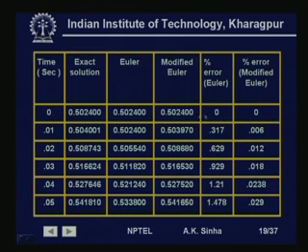If we do this, then we can see that if we are using Euler's method, we will get the values of delta like this at time 0, at 0.01 seconds, 0.02 seconds, 0.03 seconds, 0.04 seconds, 0.05 seconds, and so on. Whereas, if we are using the modified Euler method, we will get the values as shown here in this table, that is 0.5024, 0.50397, 0.508680. These are the values that we will get when we are using modified Euler's method, and these are the exact solution values for this system of equations.